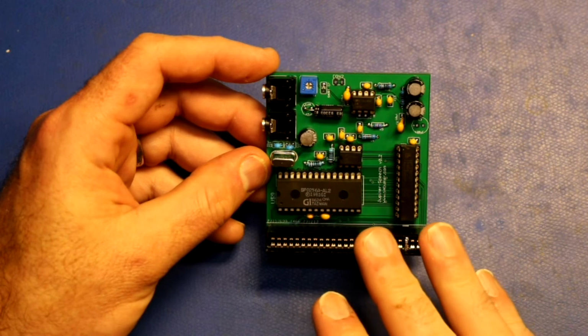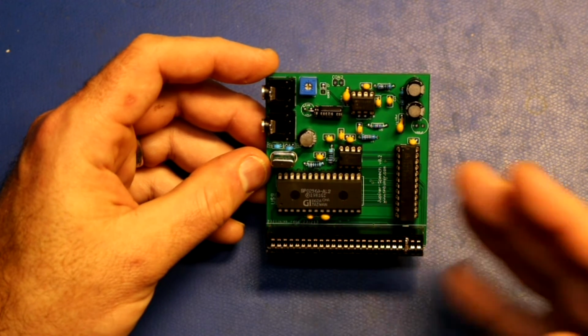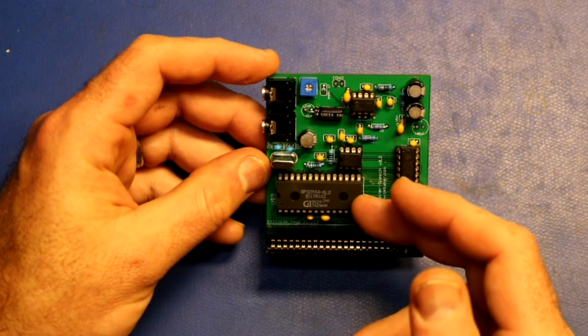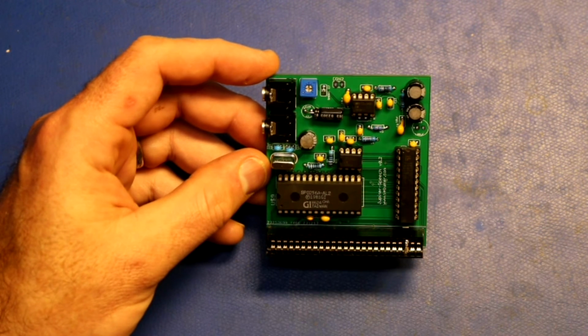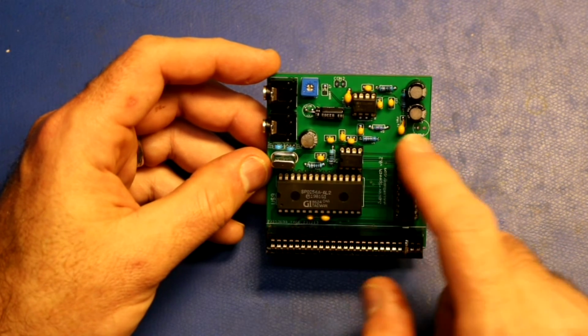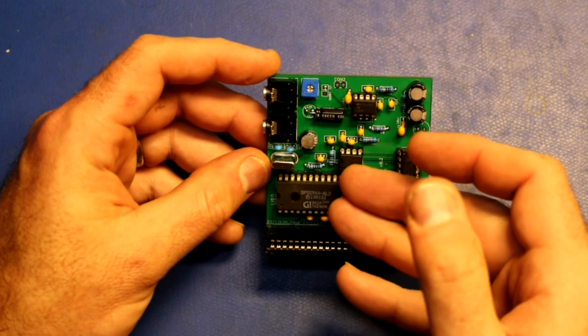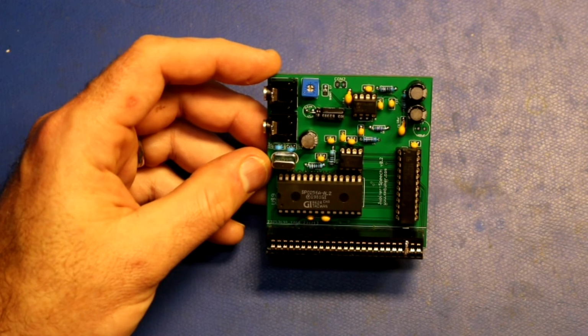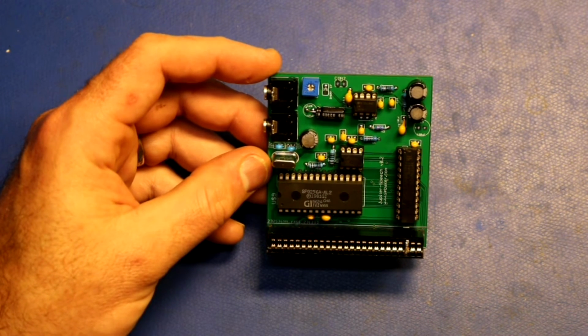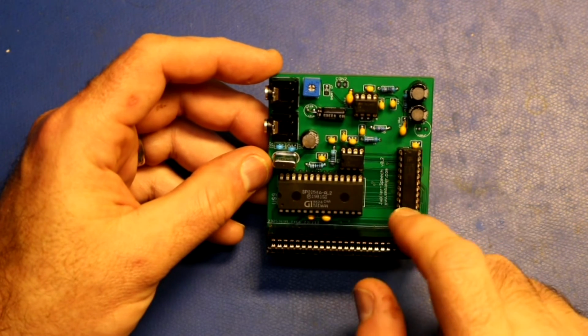It's very simple to interface with the bus. You've got some data bits, bytes. You just put them on a port. You can write the port and tell it to load into the speech synthesizer, and it will speak the phoneme. To get your status back, you just read from a port, and you can read back whether the speech synthesizer is busy. So you wait while it's busy, and when it frees up, you send out the next phoneme. So you're kind of in a polling loop. You could use interrupts. I chose not to use interrupts. I just did polling. And again, I've got one of my GAL